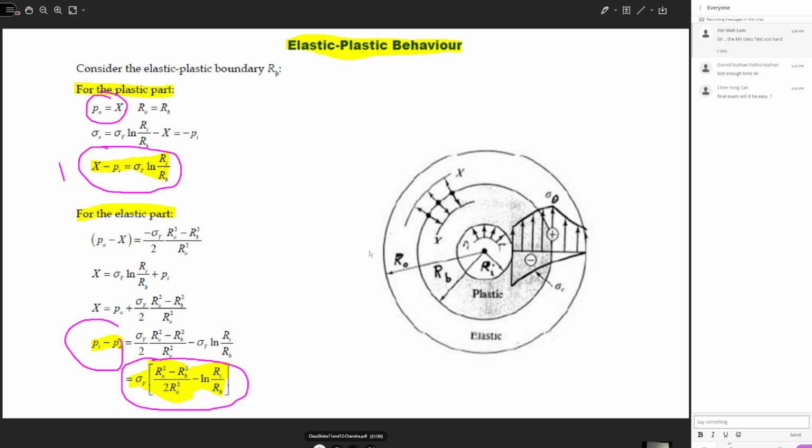So basically, in thick wall cylinders, we can study how to calculate the radial stress and tangential stresses under different conditions using a linear formulation and nonlinear formulation. All the formulas are in terms of inner pressure, inner radius, outer radius, and where you are calculating, that is in terms of small r.